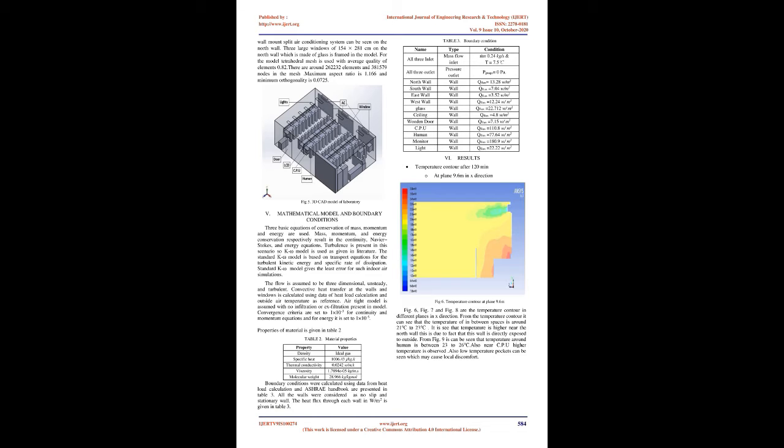A, room sensible heat. A1 equals solar gain through glass equals 595 BTU/HR. A2 equals heat gain through walls and roofs equals 15,168 BTU/HR. A3 equals sensible heat gain from humans equals 13,000 BTU/HR. A4 equals appliance load equals 21,216 BTU/HR. A5 equals lighting load equals 4468 BTU/HR. Total room sensible heat A equals A1 plus A2 plus A3 plus A4 plus A5 equals 54,446 BTU/HR.